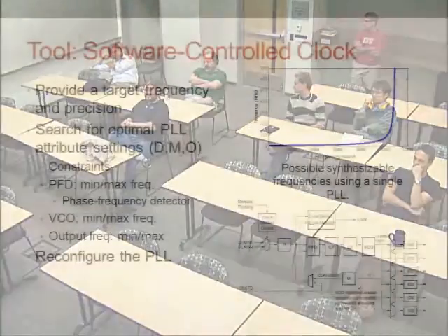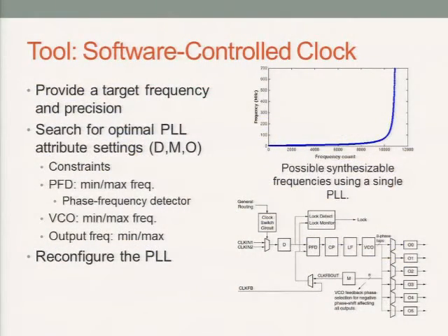For that matter, it's a matter of input vector coverage, right? In a reasonable amount of time, how many test vectors do you feed this thing in simulation? I guess that's why I was asking. You want to simulate it first, right? To some extent. That's kind of where the specification finding comes in. You've simulated it first, and it seems pretty good, but let's run it through this, and this is kind of a runtime thing. It also allows you to get more coverage over more time, and there are also things you can't account for in simulation, like your interface to DDR2. That's kind of hard to simulate, or to flash.